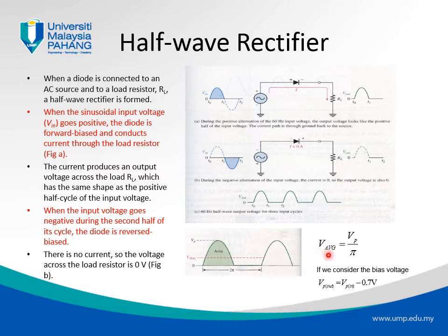One precision that we may want to take into account is that here we are considering that Vp, the maximum voltage, is equal to V input. Whereas we know that for a diode to function, V input has to be higher than the value of 0.7 volt or 0.3 volt, depending on the semiconductor that we use.